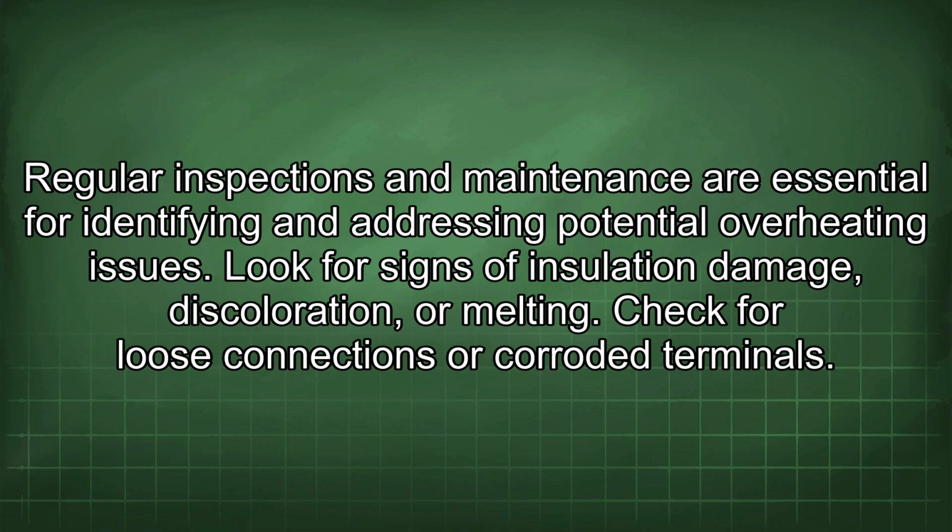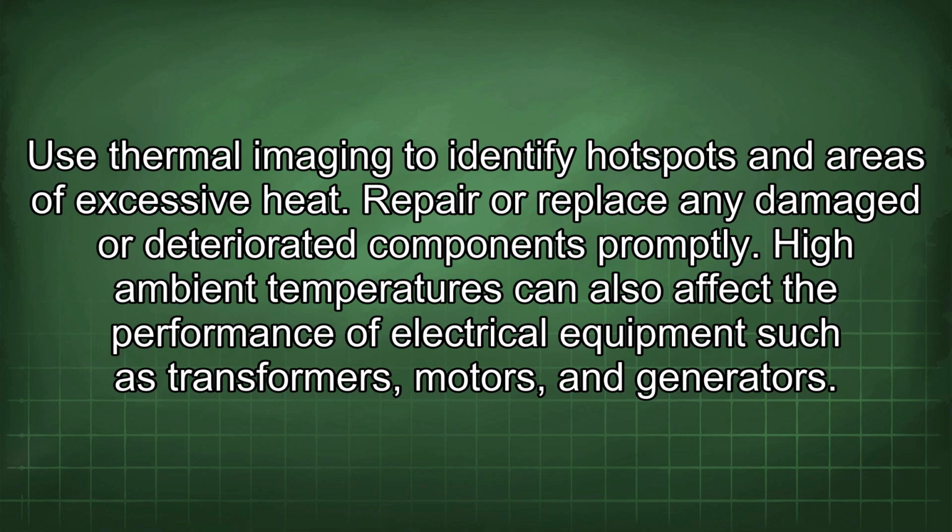Look for signs of insulation damage, discoloration, or melting. Check for loose connections or corroded terminals. Use thermal imaging to identify hotspots and areas of excessive heat. Repair or replace any damaged or deteriorated components promptly.